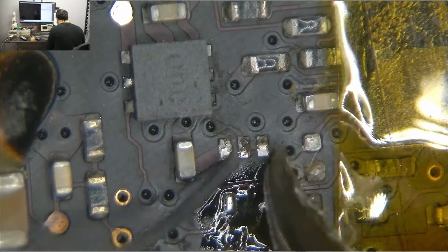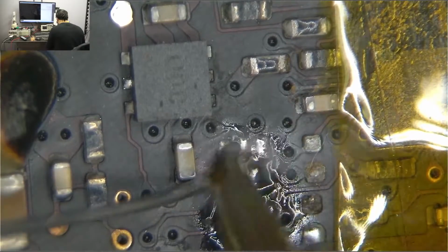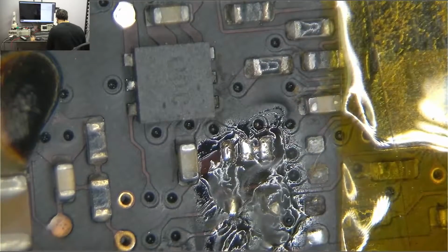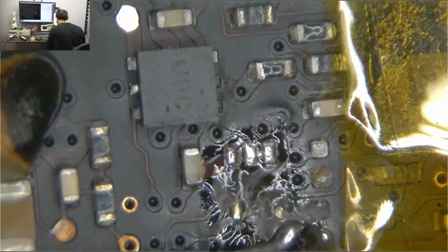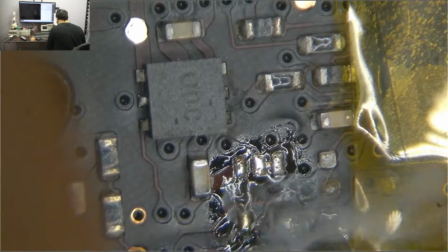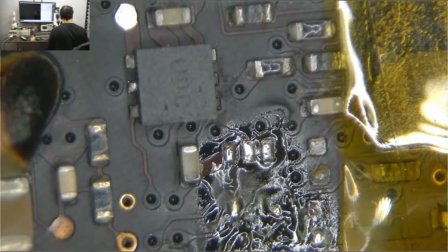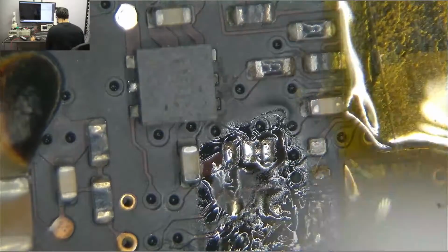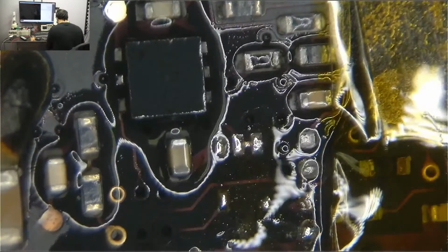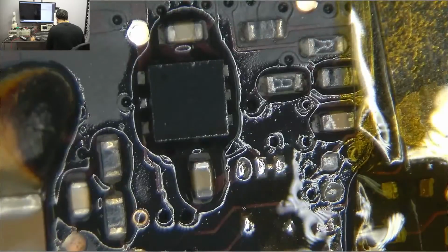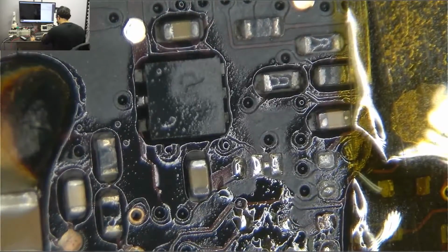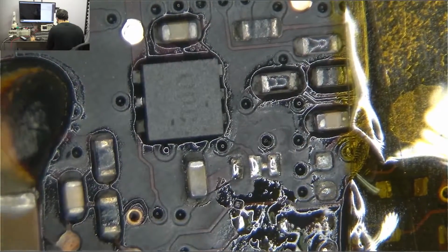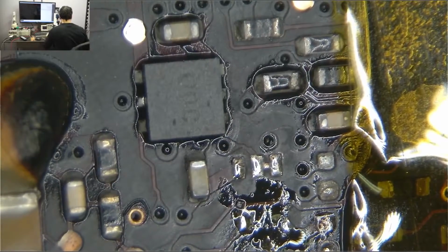So what I'm doing right now is I'm just going over these solder pads with the iron, and there's one pad in particular that's interesting to me because it's kind of destroyed. I'm probably going to be running a wire to it. So let's just see what this looks like after a little bit of cleaning. Yeah, this looks like crap. You can tell that there's a pad right here that's scratched away, and this actually got stuck on my tweezers. So let's see what we can do about that pad.